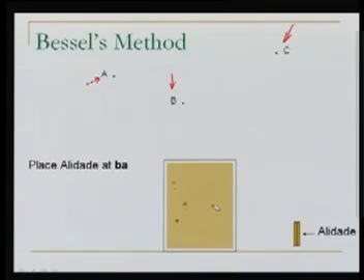In order to do this Bessel's method, we follow some steps, and please follow these steps carefully. We are going to list those steps here. You can find these steps also in any of the textbooks, but following those steps carefully is very important, number one. Number two, to understand the concept, as we knew in the tracing paper method, we are trying to realize the horizontal angles formed by those control points at the point where we are standing.